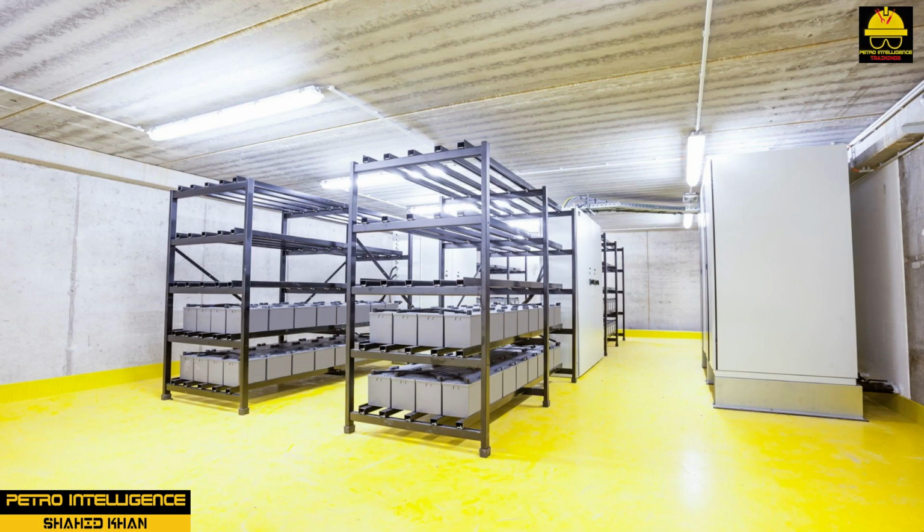The critical instrument systems are supplied with power through an uninterruptible power system, UPS. This system contains batteries, a battery charger, inverter, static transfer switch, and manual bypass switch. This backup system ensures that there will be no interruptions to alarms, computer control systems, and all other instrument systems.